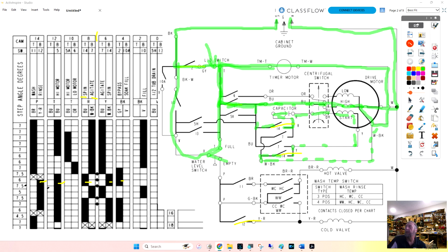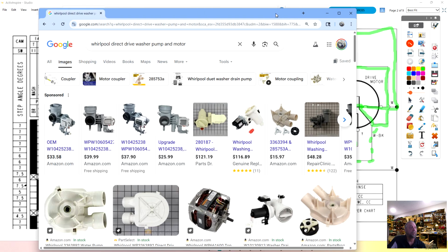If you look here, I don't know if I can find one where it's actually connected, but this is the pump, and you can see this D-stem shaft here in the bottom left. It slides on this motor right here, and this motor, which is the washing machine motor, is what is turning this pump. When I turn one way, water will flow in here and go out the other, but if I turn the other way, the water will not drain.